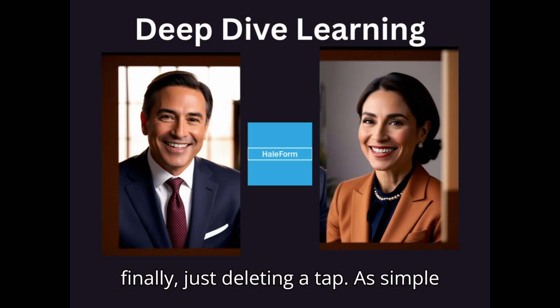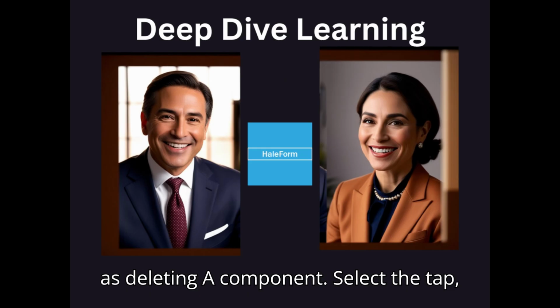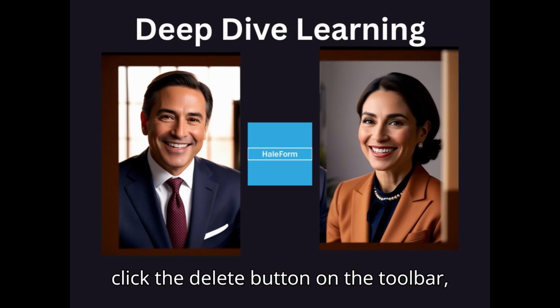Okay, and finally, just deleting a tap. As simple as deleting a component. Select the tap, click the Delete button on the toolbar, gone.